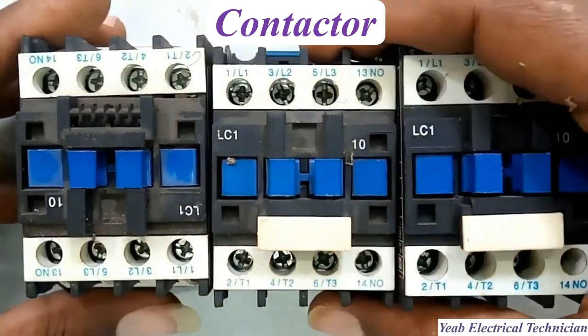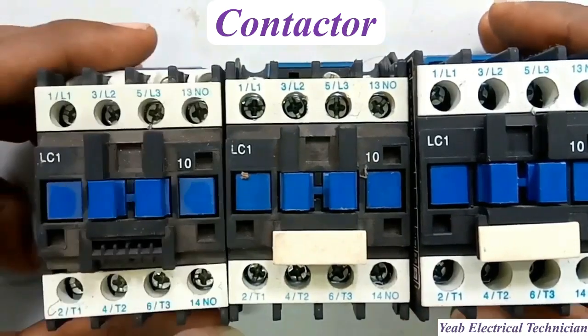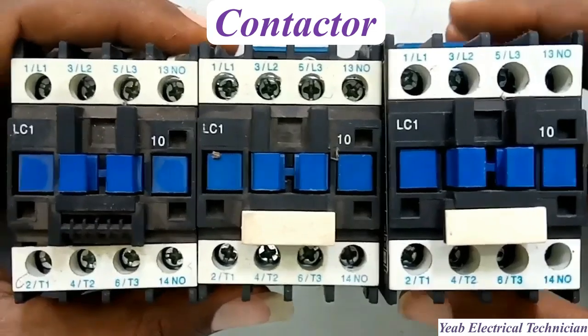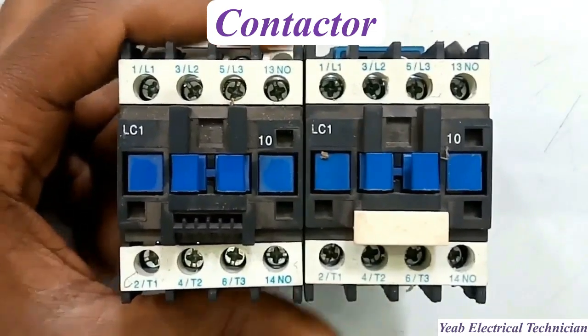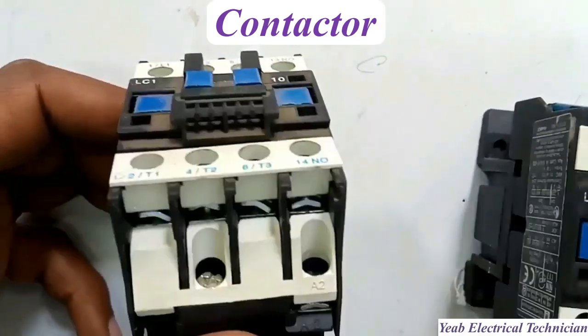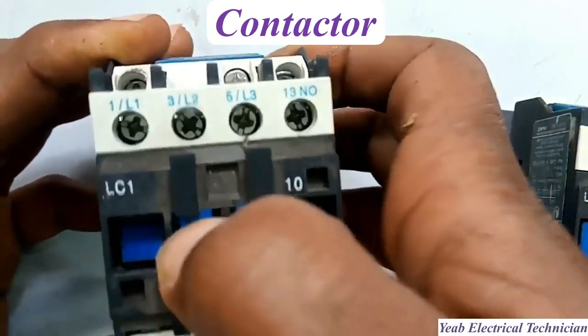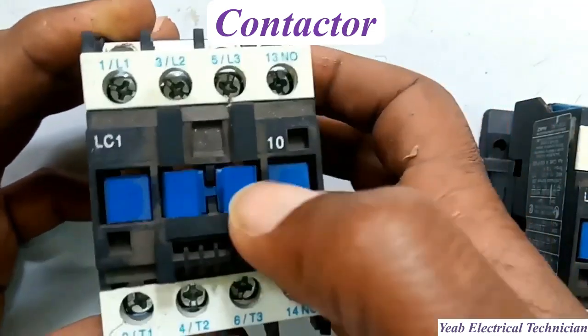The fourth question, what is a contactor used for? A contactor is an electrically operated switch used to control high-power electrical loads by safely switching circuits on and off. They are commonly used for industrial applications like starting electric motors, but also control other high-current systems such as lighting, heating, and high-voltage AC equipment.